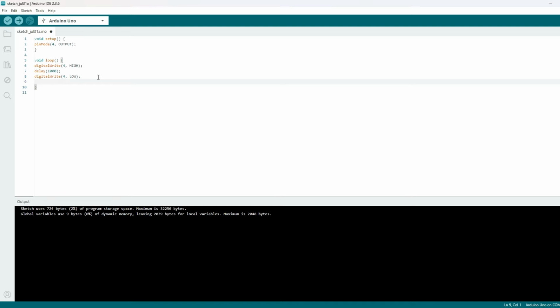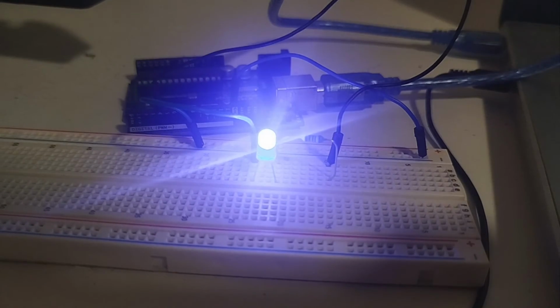And then we're gonna do another delay, and you'll see why now. Say another second. You can actually write whatever you want. Say 386, and here 946. But no, cool. So what it'll do now is turn our LED on, wait for 946 milliseconds, turn our LED off, wait for 386 milliseconds, but then remember that this void loop runs repeatedly. So it'll come back here, turn our LED back on, off, and we now have code for a blinking LED.